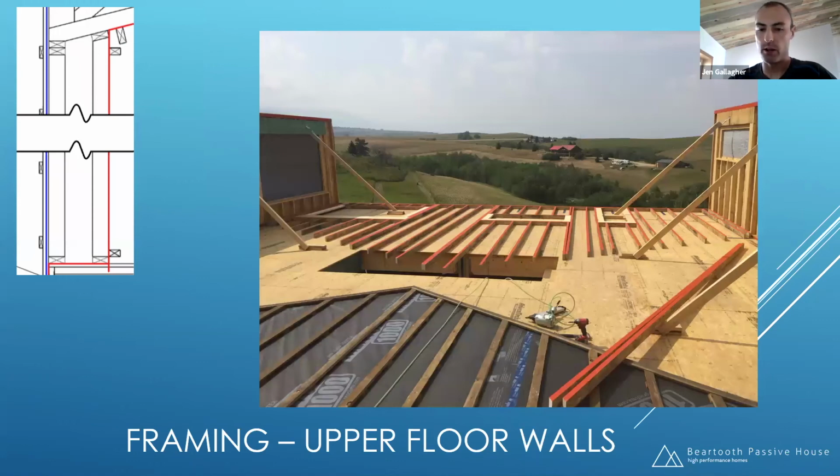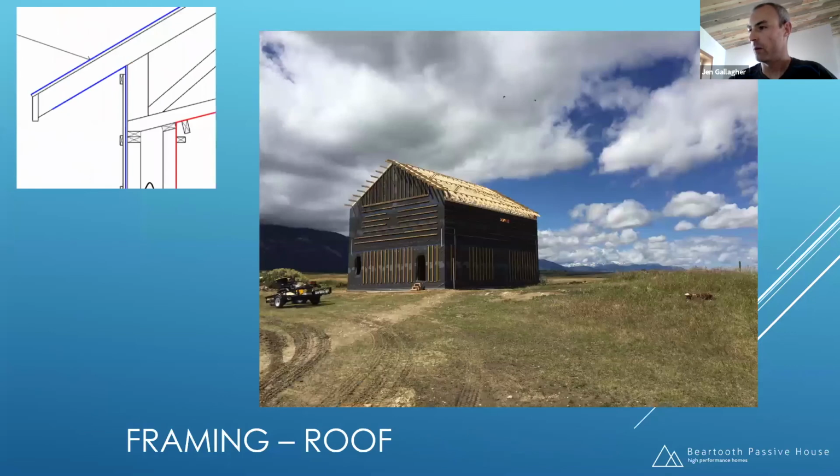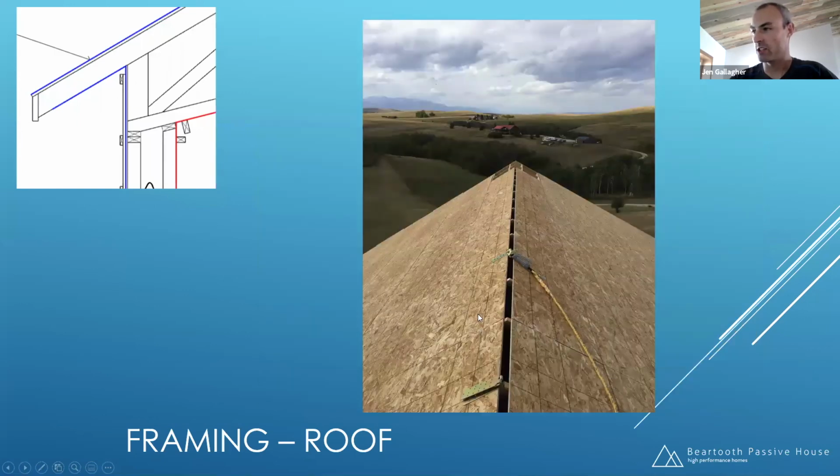There's a gable end wall, balloon framed there. And we left the wall. We put our roof trusses on. That was a pretty quick transition. For the roof, we just have a regular vented roof. So I've got my ridge vent right here.